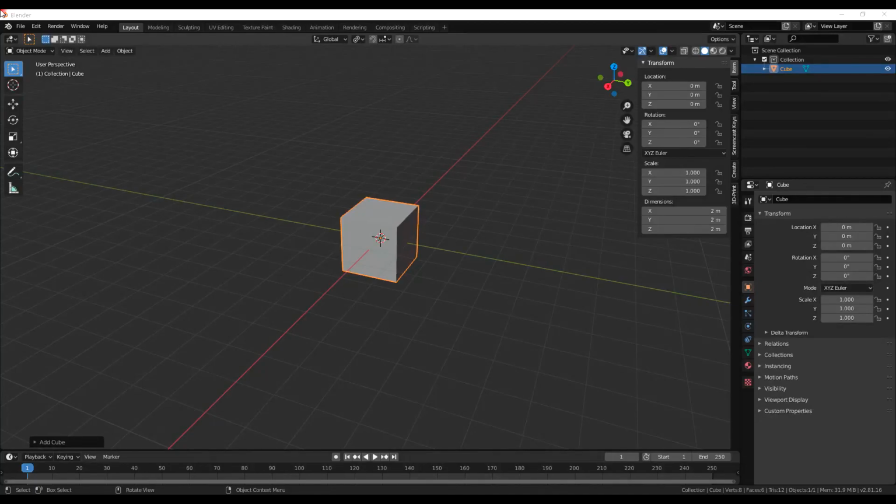This is video 4.2 of the Blender 2.80 course, and this time it's about snapping. Snapping is useful when you want to make sure that something that you place is exactly next to something else, or you want to align something so that you only turn it at a certain degree, like 5-degree increments, or you want to scale something so that it is fixed as to how much it scales.